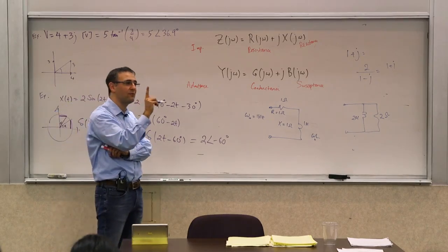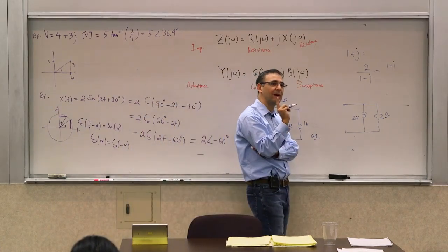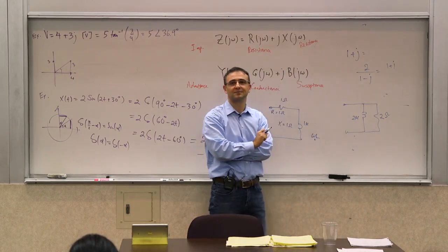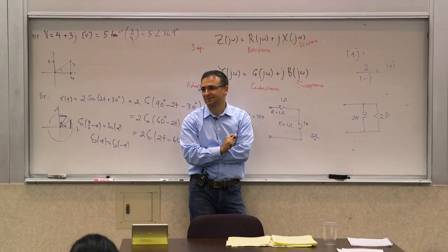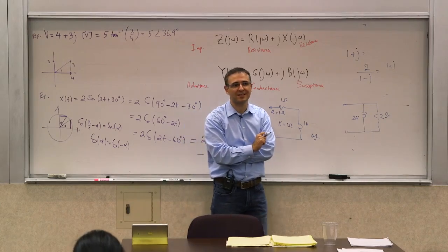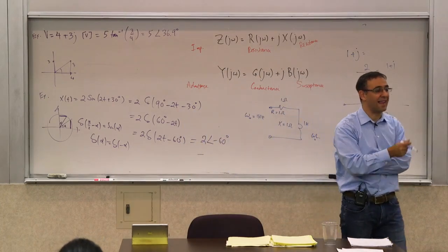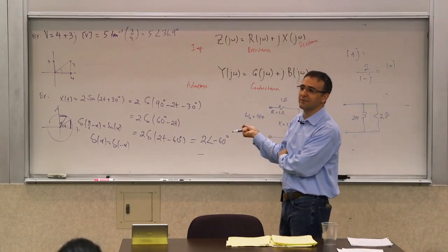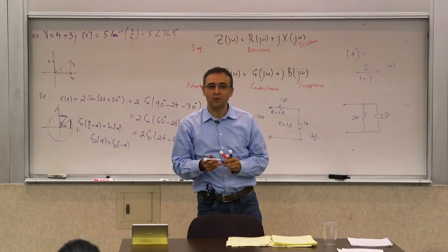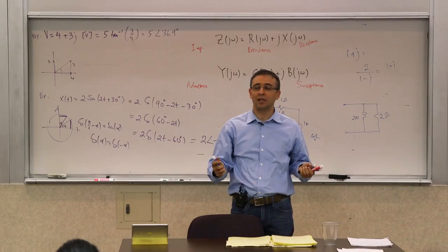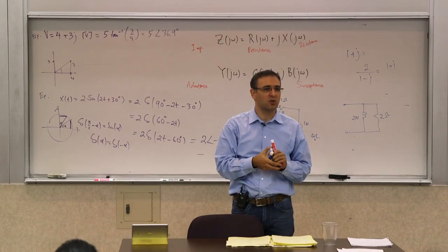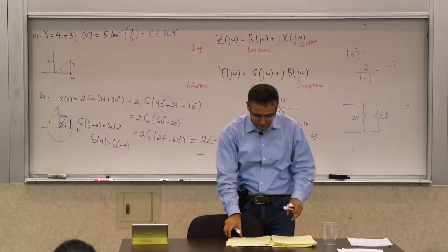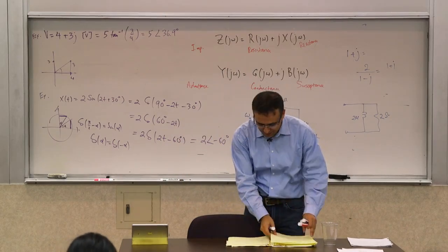So if you're operating at a very well-defined narrow frequency, you can replace this network with that network, because they would produce the same impedance at that one frequency. But their behavior versus frequency is different. If you're operating at a single frequency, then you have a lot more leeway, because you can play all these games, because you're just trying to match 2 numbers to another 2 numbers, right? Okay, so that's for that.